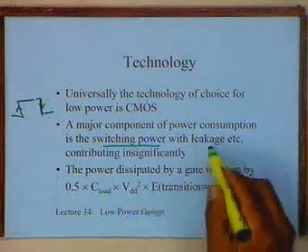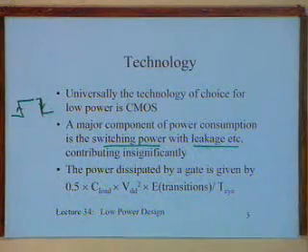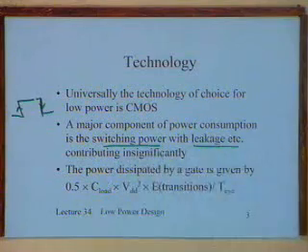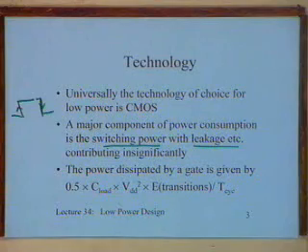So the switching power, of course there is some leakage and so on, so it is not that it is not there, but in most cases the leakages are substantially lower, and the only significant part of the power consumption is the switching power. The transitions are the ones which account for the switching power, which implies that we can talk in terms of techniques to address this issue of reducing the number of transitions. We can see how we will do that.